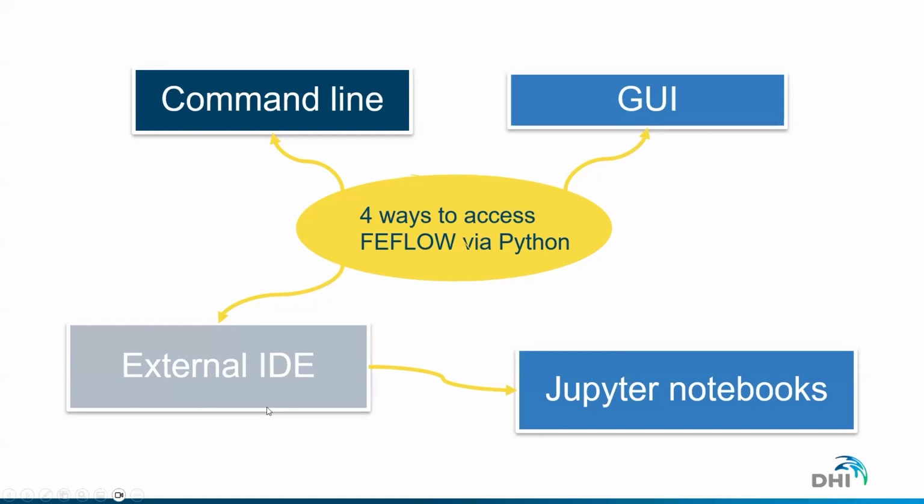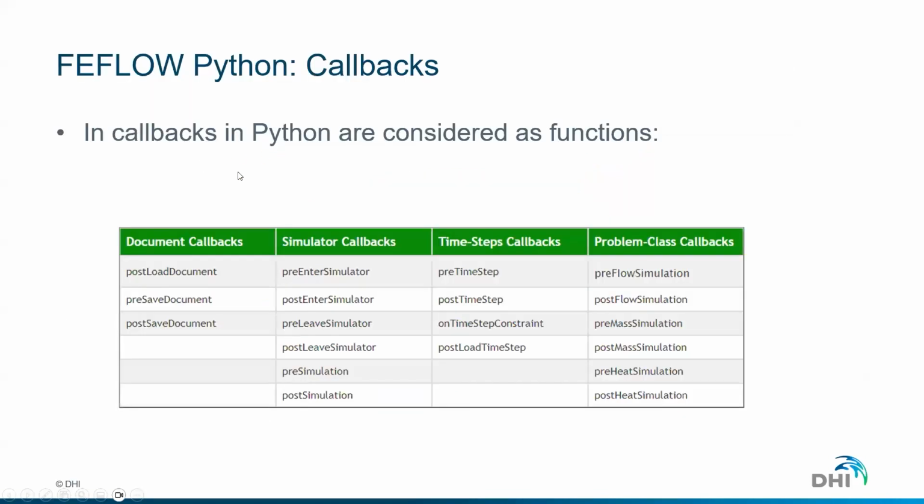It's not limited. If you call the FEFLOW console, so you call feflow81c.exe -python, it will initialize the Python installation. It also comes with a tiny FEFLOW Python installation, so that you can also run some Python commands through the FEFLOW console. That's quite interesting.